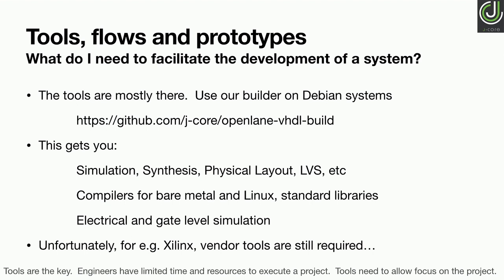It takes GHDL. It will integrate GHDL with Yosys, with ABC, with NextPNR. It'll give you all of the SPICE simulators that you need to do the analog side. It gives you all of the PDKs you need in order to target Sky130. Everything comes out of that, and you can do both the calculator design and prove that it works in real hardware, and then you can tape out on Sky130 just with that.